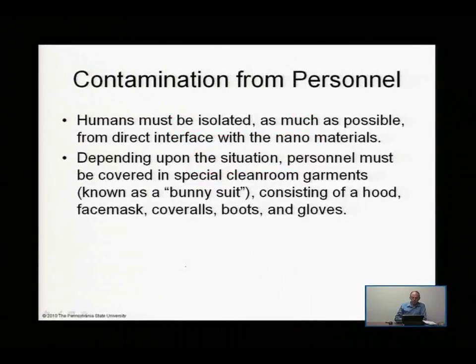Well, as we said, people are a major source of contamination, and let's go back to that idea. So we really have to make sure that we can isolate humans from the nanomaterials and the nanoproducts that we're working with. So depending on the situation, people need to be covered in special clean room garments known as bunny suits, which consist of a hood, face mask, coveralls, boots, and gloves. Now, this is if you're going to use a clean room.